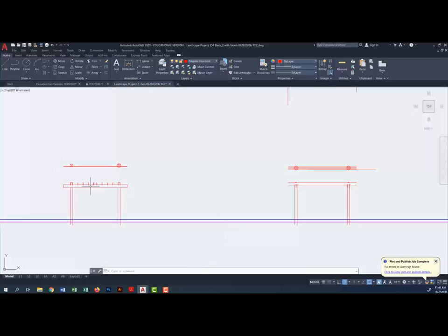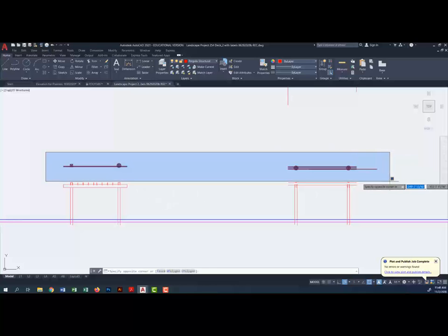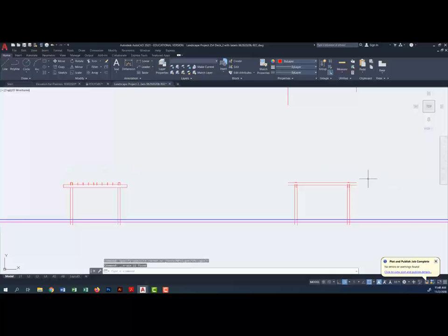So I have the lintel in my left view, the side of the lintel, and therefore I see the flat with the joists. I see the ends above. In the other view, what do I see? I see only the ends of the lintel and then the flat of the ceiling joist above. And that all lines up, and that's what it should do, is line up. And basically I've got the upper half of my elevation drawn except for the end cuts.